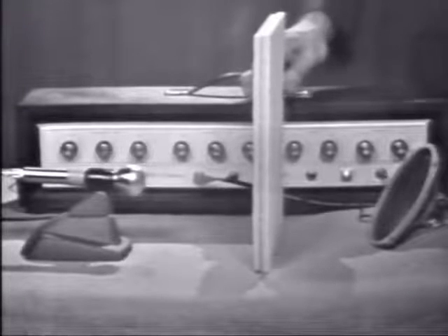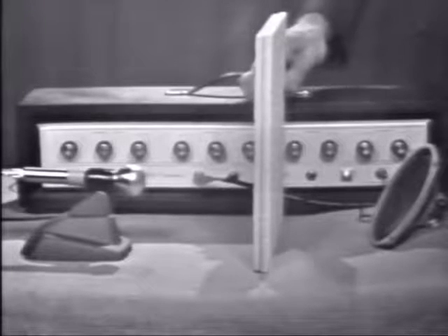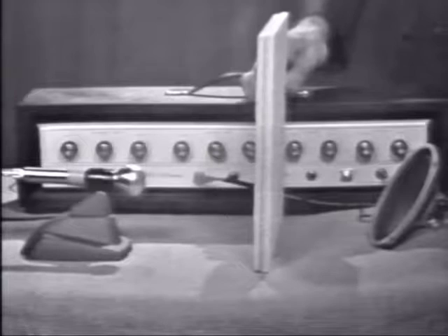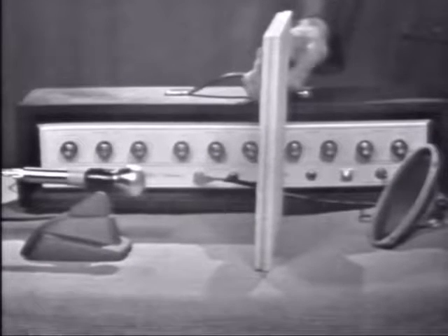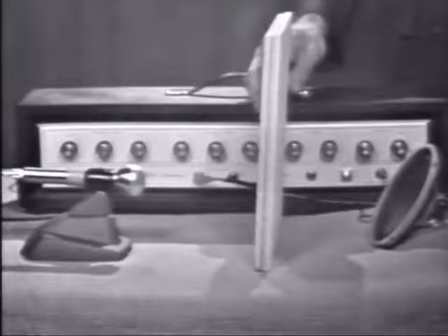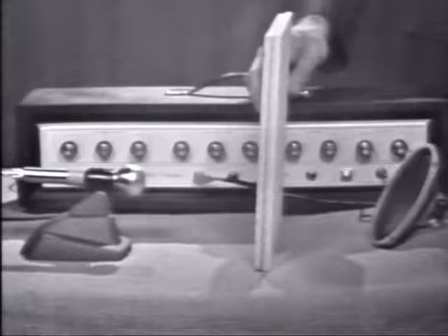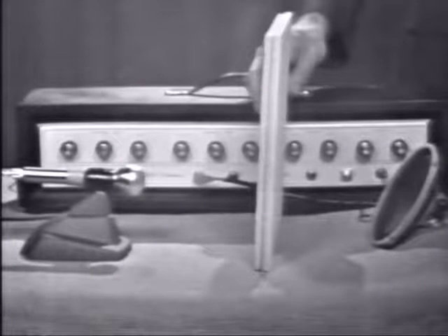And if allowed to continue, very high oscillating currents are built up that may damage circuit components. For this reason, the amount of feedback must be controlled in an oscillator. The correct amount is just enough to overcome the losses in the circuit. Any amplifier will oscillate if feedback occurs. But what is the frequency of oscillation?